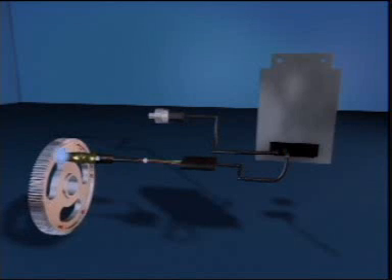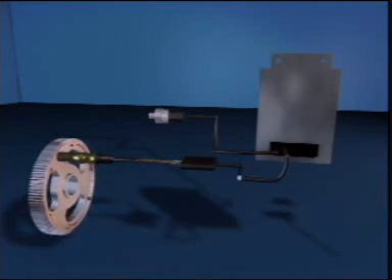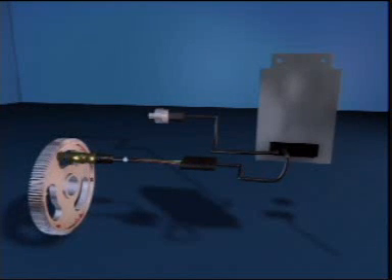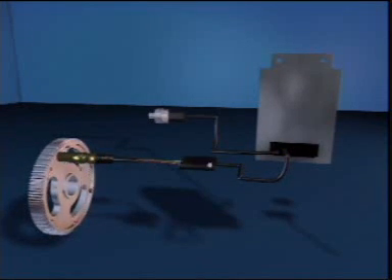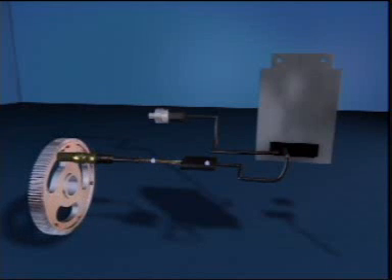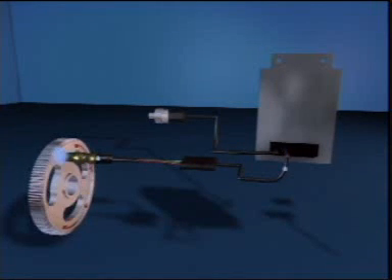The engine position sensor measures the position of the engine camshaft by the use of a variable reluctance sensor and 7 cast protrusions located on the rear of the camshaft gear. Whenever the cam gear protrusions pass the engine position sensor, the deflection in the sensor flux lines generates an alternating current signal to the ECM.